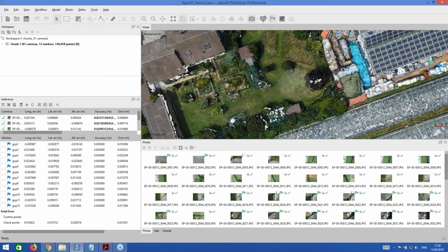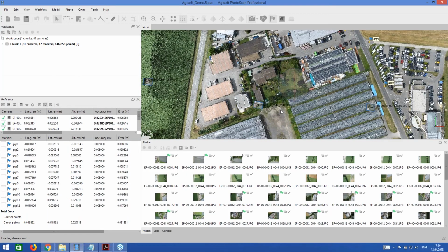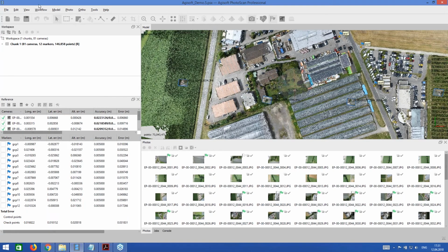Based on the dense point cloud data, several products can be created. Let's see them in the workflow menu. Those are polygonal model, mesh, tiled model for huge data sets, and digital elevation model. I assume that the digital elevation model is of most interest to the audience today, so I go straight to demonstrating the procedure of how to generate it.